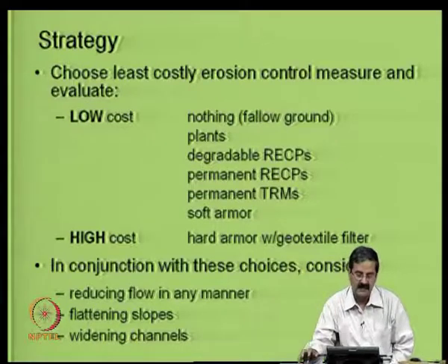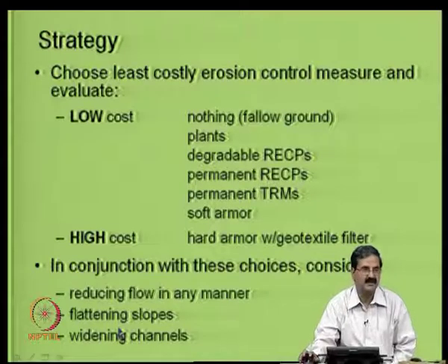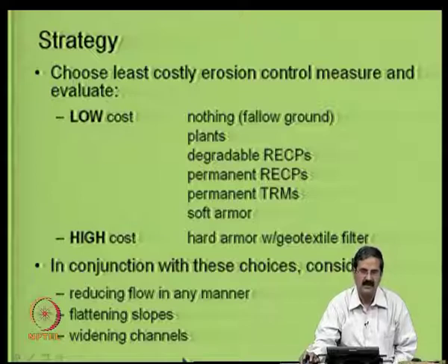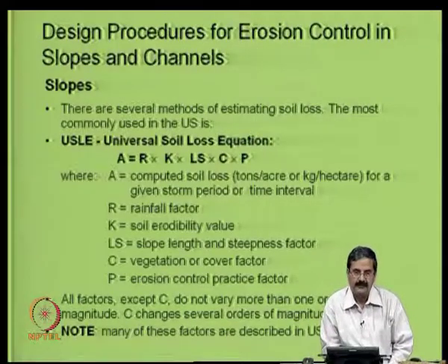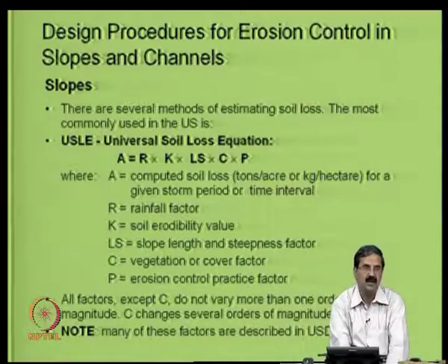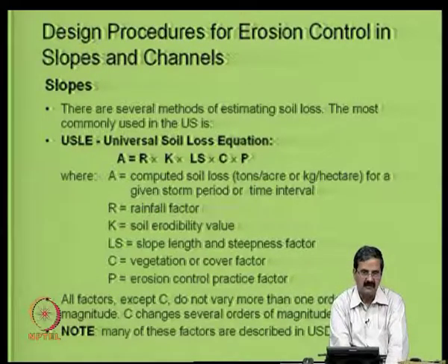Okay. Then sometimes in slopes, widening or flattening of the slope is another variable. Widening of the channels, because once you widen, the velocity decreases, then it is nice. So, in fact, people try to use many concepts in these erosion control design procedures. One common thing is that they try to estimate soil loss. Actually, estimation of soil loss is something that is very important.